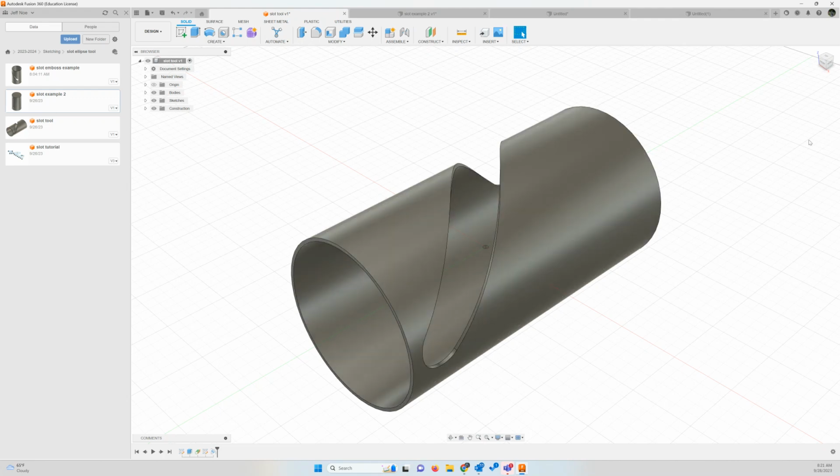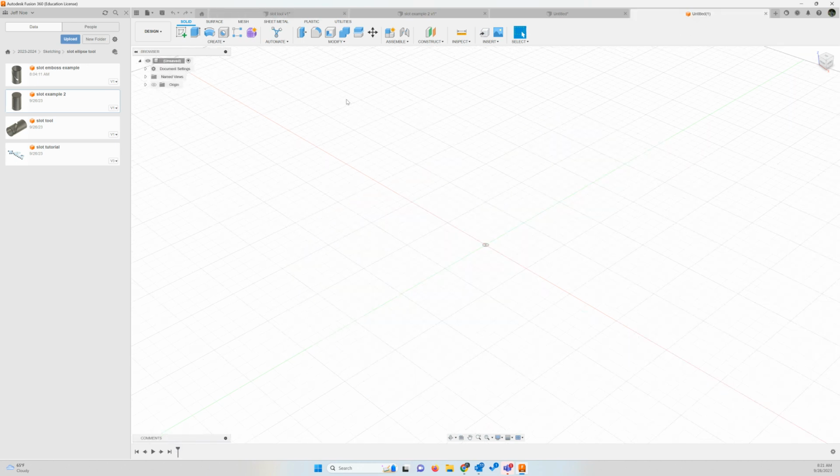We're going to extrude in a symmetrical direction. It's 150 millimeters in total. We're going to define it as the total length. And then we will create our tangent plane again and emboss the slot onto the face.